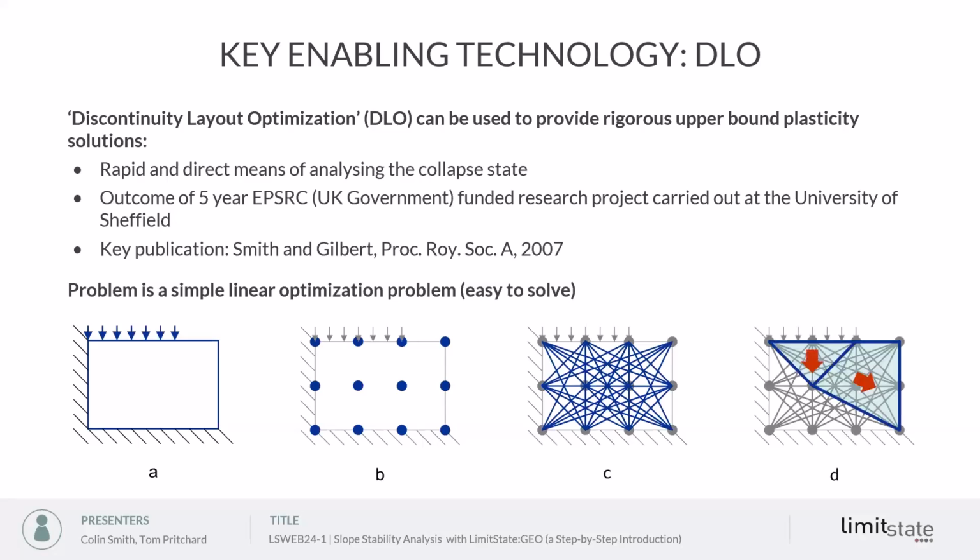In this case, it's a very simple mechanism involving 6 lines out of our original, I think, 66 possible connections that we have. Generally, we're going to be solving problems with hundreds of nodes or thousands of nodes and millions or tens of millions of potential slip lines, and those can solve in a matter of seconds generally on modern computers. The examples I was showing, we're typically modeling with 500 nodes. Generally, we might model with slightly more, but just for the purpose of illustration, I'd be looking at that. But the accuracy will depend on the number of nodes that you employ.